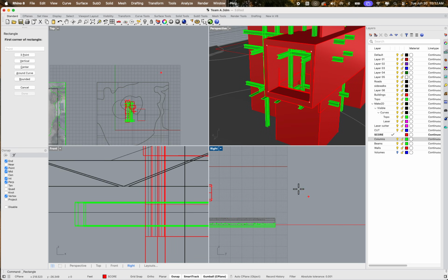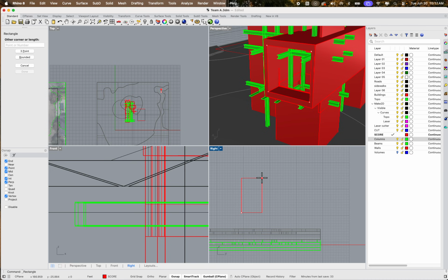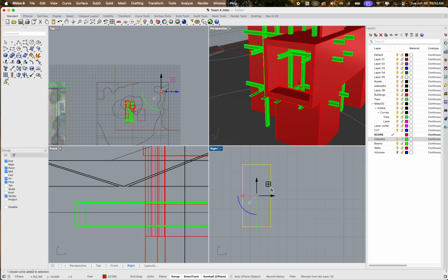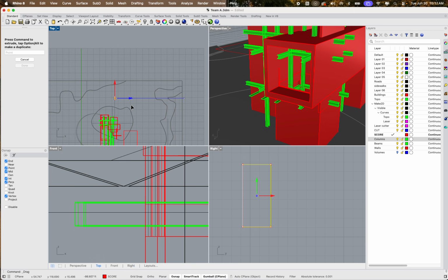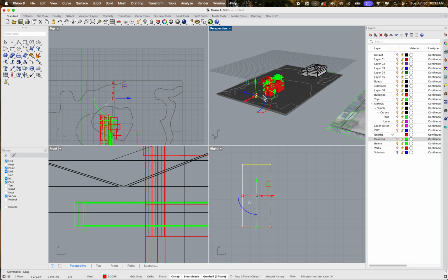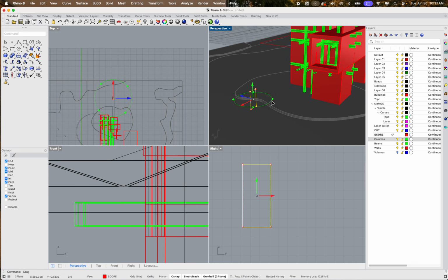In my case, I'm going to make a door off to the side. We know that a door is essentially 36 inches, usually minimum for ADA, and then also about 6 foot 8 inches, right? So we can actually make a pretty typical door. And if you don't know those sizes, look them up, right? I mean, no big deal there. We got the internet. So I have a door, or at least the cutout of a door here, and basically want to get that into position.